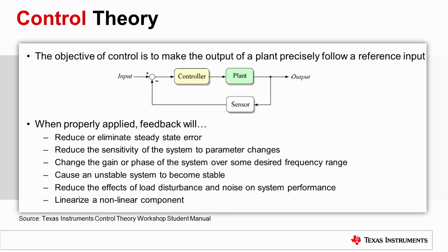This implies that if your input voltage and output voltage stay fixed, the duty cycle of the buck converter should stay constant. In an ideal, lossless system, this is the case, but unfortunately power supply circuits are not lossless. The losses increase as more load current is pulled from the output, which in the case of a fixed duty cycle system will cause the output voltage to sag as load current increases and vice versa. To account for changes in load current, a control system needs to be implemented to adjust the duty cycle and regulate the output. A controller paired with negative feedback is used to do exactly that.